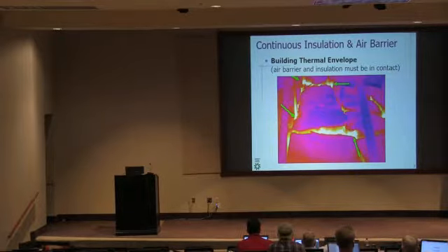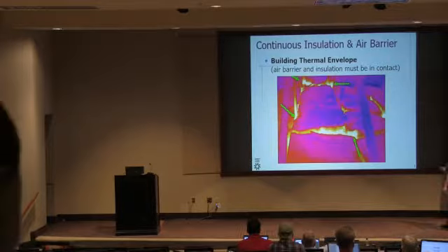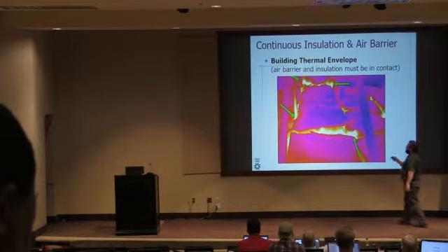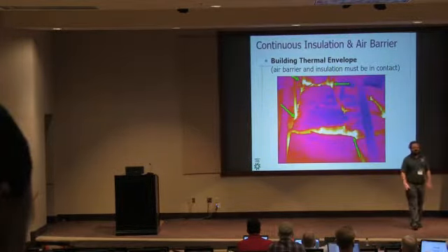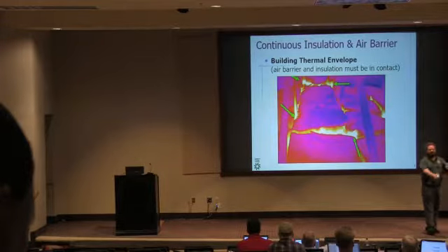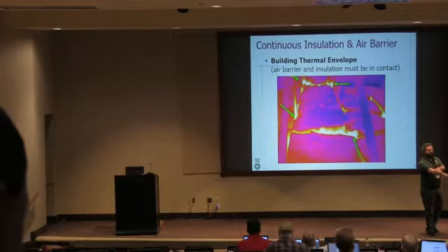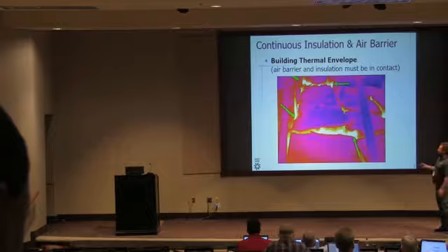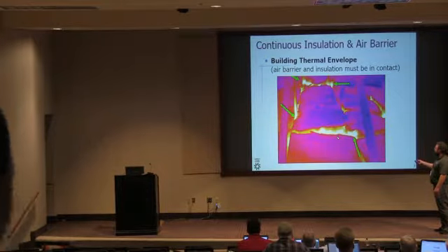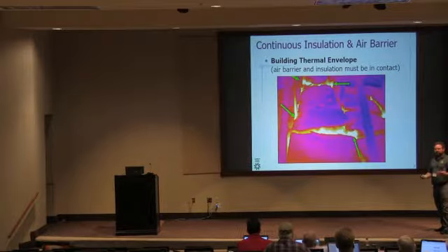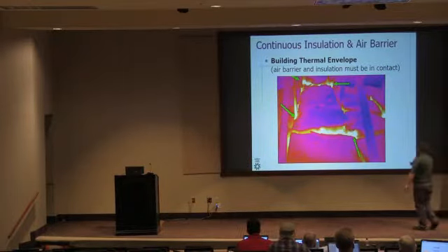That surface gets warm, and then it starts to radiate heat because this bat product is not an air barrier, and it doesn't provide resistance to conduction unless it is in contact with an air barrier. So when it's sitting like this, and it's not in contact with that sheet good below it, it really has almost no effective R value, very little effective resistance to conduction.